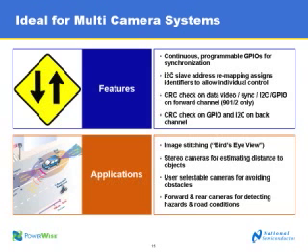And then the CRC checking on the video synchronization, I2C, and GPIO data. So basically, if there is an error, that's flagged to the host processor, and the processor can react accordingly to make sure that any data that's used for safety decisions is correct. And then finally, the CRC checking on the GPIO and I2C on the back channel data.